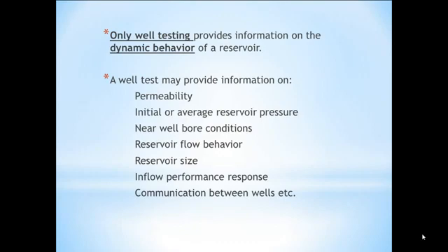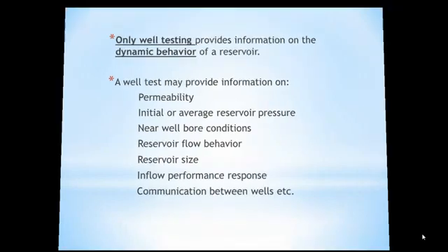So basically what well test data may provide is information regarding permeability, initial or average reservoir pressure, near wellbore conditions such as skin or stimulation, reservoir flow behavior, reservoir size, inflow performance response, communication between wells, etc. All this information depends on the design of the well test. So for a particular design, maybe we can get a few of these, and to get the rest of the information we need to perform a different type of test.